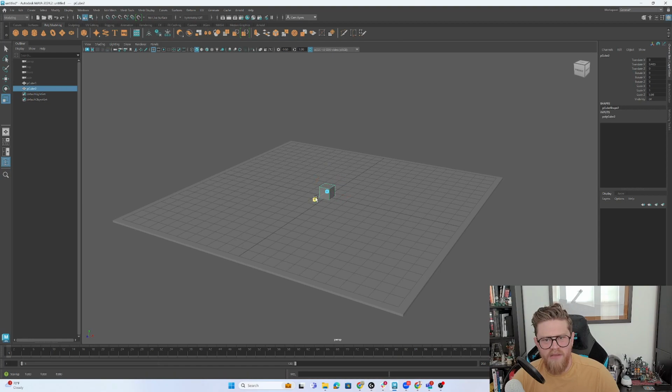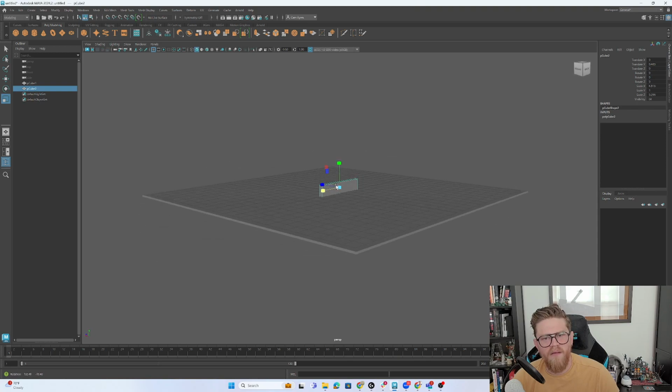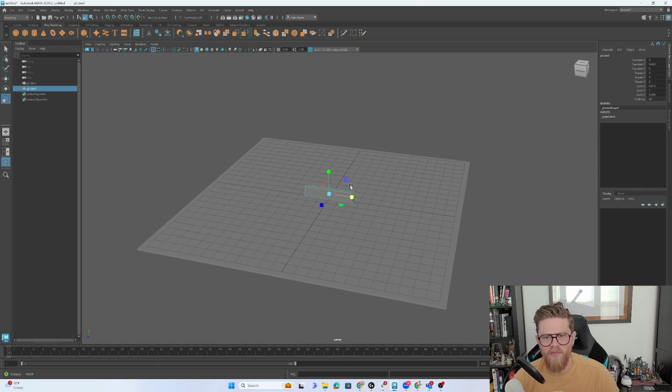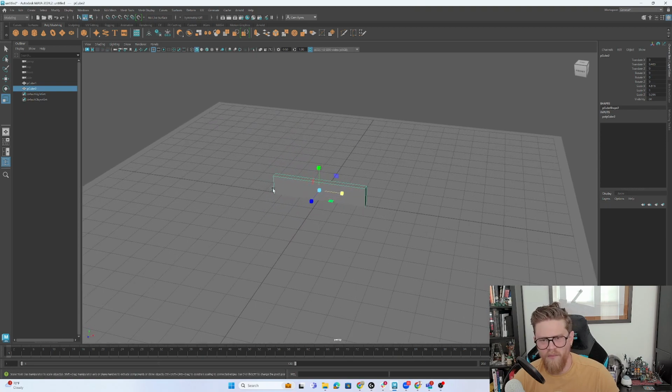So let's make the back of this by shrinking the width of the back plate. And then essentially we can go about this two different ways to create end caps. I can either make two new cubes, position them accordingly, and have it all just kind of look good enough. Or I can come in here and do a mesh tools, insert edge loop, and then come over here and just do something that's relatively close.